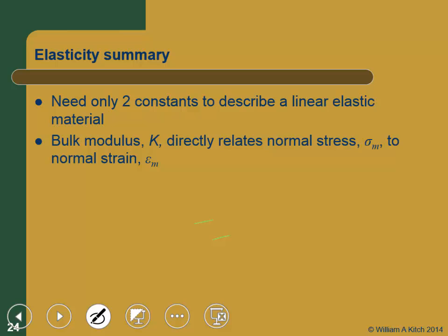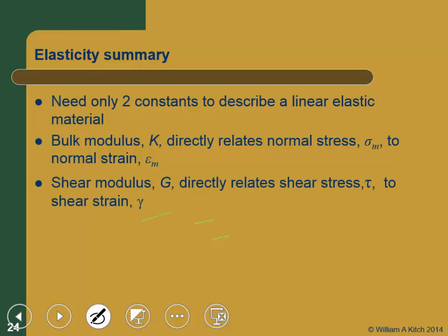If you want to talk about shear stiffness, you should be talking about the shear modulus. So the shear modulus tells you how easy it is to deform in this direction. And the bulk modulus tells you how easy it is to squeeze the ball and make it smaller. I like those conceptually. They have real meaning to me. Young's modulus is some weird combination of those two things.